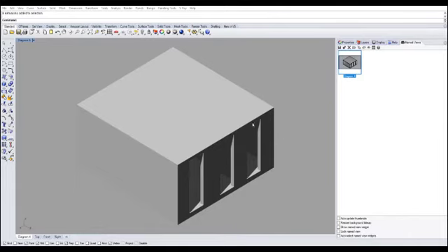Now the next thing is, of course, there's a thing called render output, which sets the size of your render based on the image width and height. For now, let's leave this as is. But you know where it is, just in case next time you want to make a smaller or larger render, you simply type in the size that you would like. There are various standard sizes to make renders. Please seek those guides. Now this is ready to go.